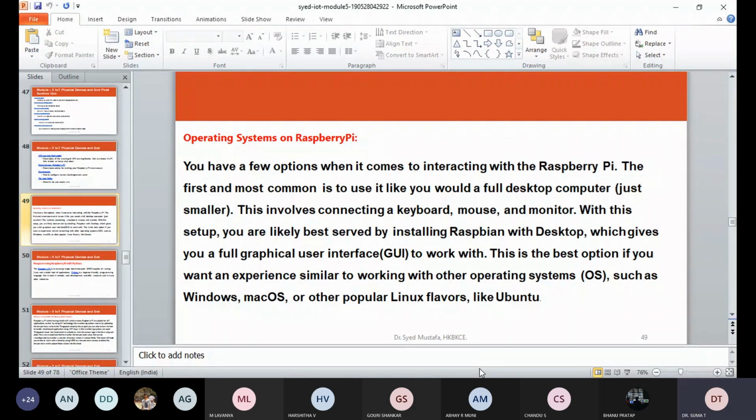Once the SD card has been formatted, drag all the files in the extracted NOOBS folder and drop them onto the SD card drive. The necessary files will then be transferred to the SD card. Okay. When this process has finished, safely remove the SD card and insert it into the Raspberry Pi. This is how we are going to install the operating system on the SD card.